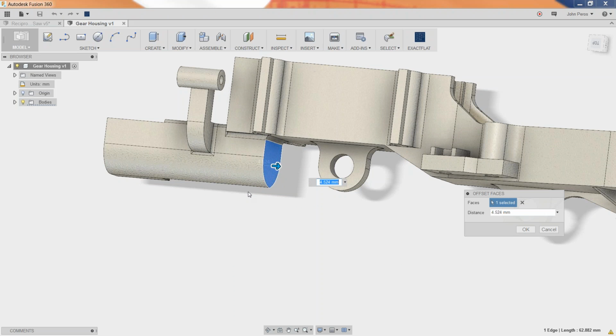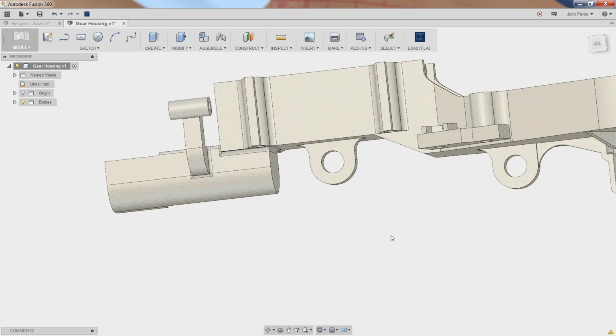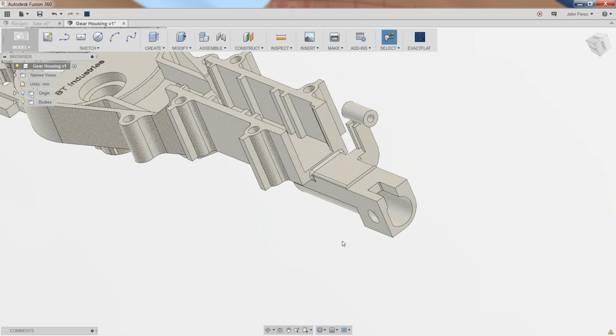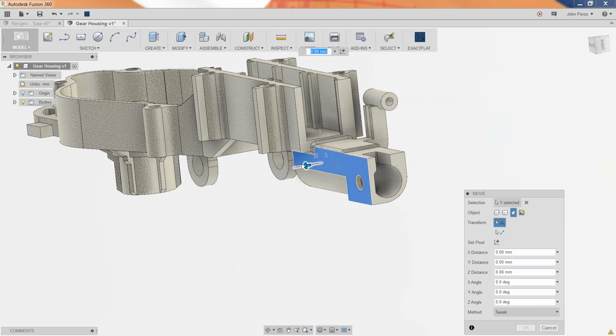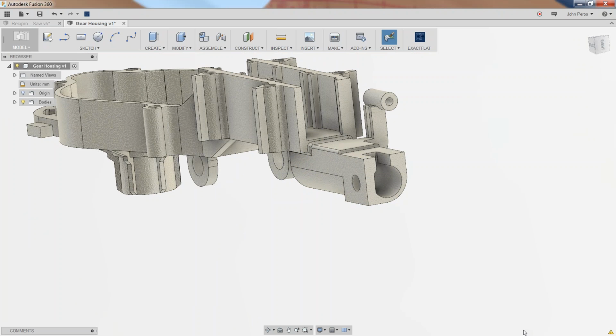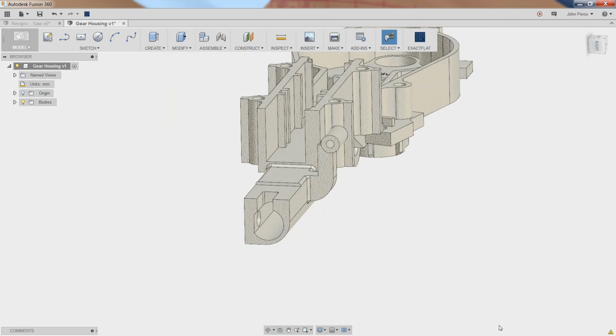And it's not just press pull, however. I can put numbers in here. I can say make that 8 millimeters longer. Maybe I want to go onto the face on the other side and make it a little bit wider so that it distributes that load a little bit better. No problem. I can make that face wider. And I can do all sorts of other things in here too.